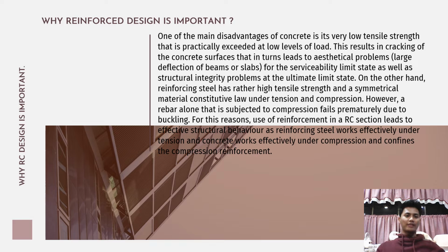Next one, why reinforced concrete design is important. One of the main disadvantages of concrete is its very low tensile strength that is practically exceeded at low levels of load. This results in cracking of the concrete surfaces that in turn leads to aesthetical problems such as large deflection of beam or slab for the serviceability limit state, as well as structural integrity problem at the ultimate limit state.